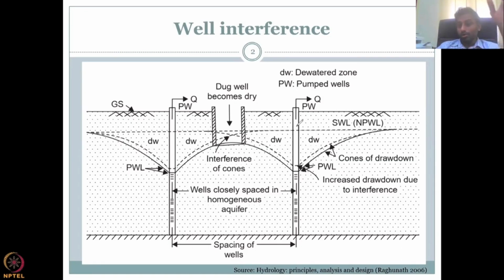Normally when you put in a bore well and see a lot of water, people just keep on using it without sustainable measures like drip irrigation. At one point it just goes dry, and when this well also goes dry, your dug well is not going to recharge that fast, because all the water that could have come from your deep aquifer recharge may not come now.